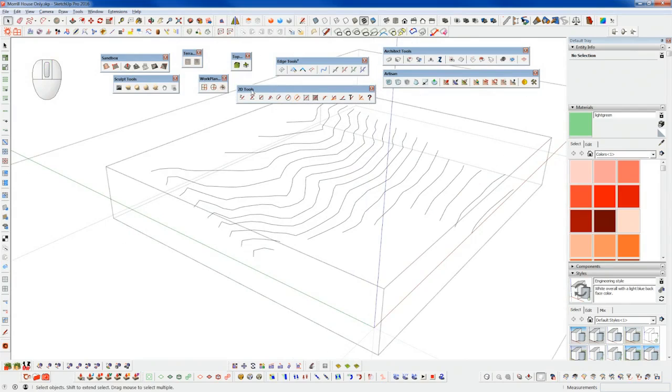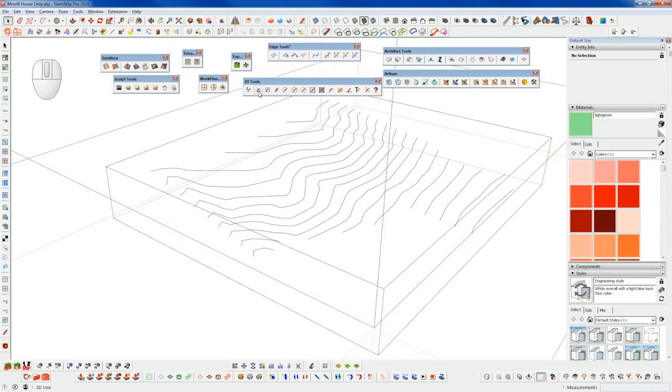So in order to do that, this set of tools comes in very handy, and this is the 2D tools. And what this does is it restricts all of these drawing tools. They all have a certain logic, and Tig wrote this plugin and kind of rebuilt the basic drawing set from scratch, and the main function is that they stay locked to a given Z height and they won't snap to other things.